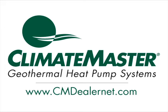How often should you change antifreeze in units? You wouldn't ever have to, because it should never reach temperatures that would ever break down. The reason you have to in automotive is because it gets pretty hot. In closed-loop geothermal, typically you're not dealing in the temperature ranges where the fluids break down. And if you're using the alcohol-based, if it was me, I would be using the ethanol alcohol and probably put in about 20 to 25%. And the alcohols don't break down as long as they're closed up and not open atmosphere. So you wouldn't really ever have to do that.